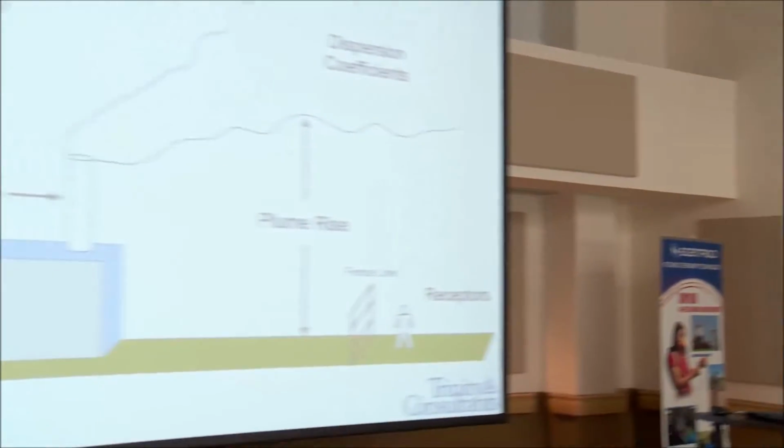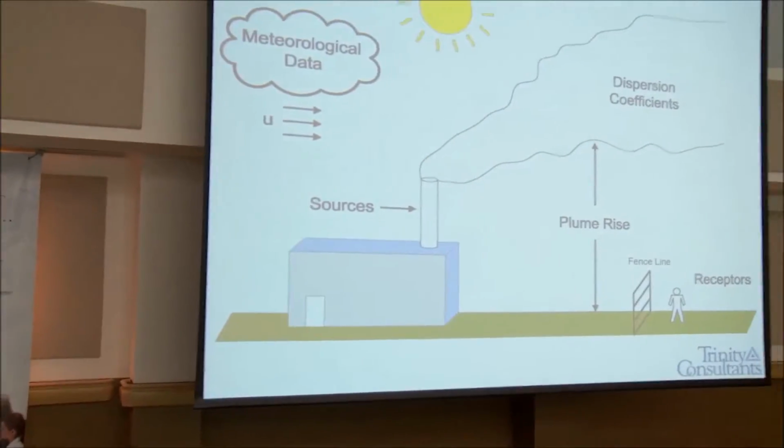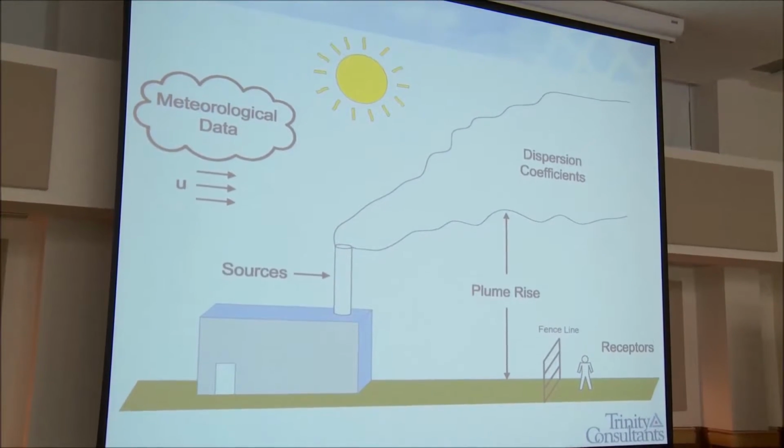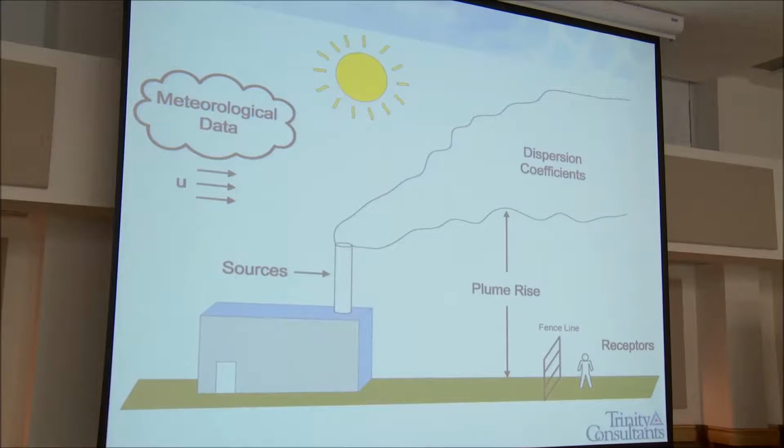All right, a simple diagram. If we had to choose a place to pick where we know the maximum concentration of odor in any given time, the easiest place to get that is actually at the stack. It's not subjected to a lot of the meteorological phenomenon that you would get at ambient locations. If you were to test at the stack, you'd have to make sure you also get worst case conditions, so the facility operating at a maximum scenario. If you're careful with your source test, you're going to have good source data.